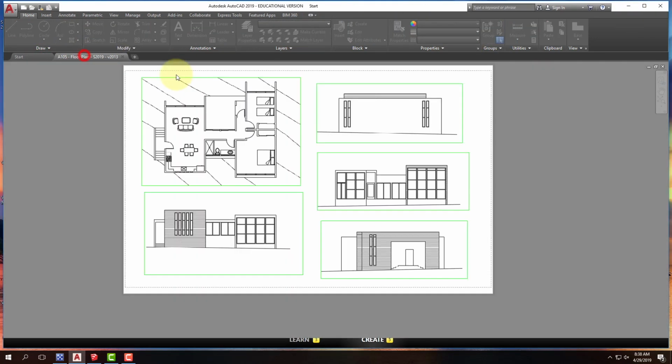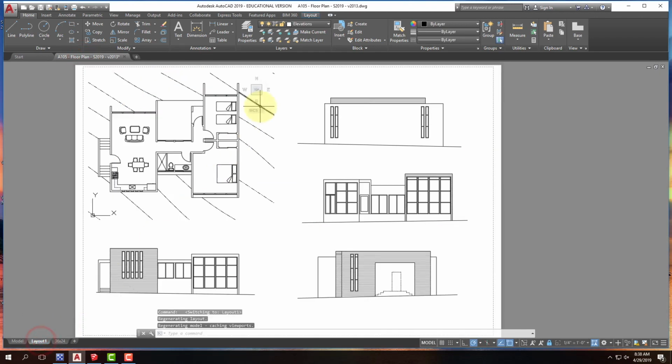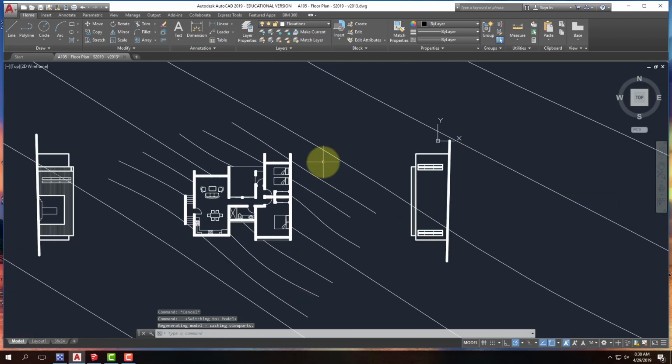When I'm working on this file, I could, in AutoCAD, go through and strip out all the pieces that I don't need. If I was in model space here, I could strip off the furniture and whatever, and I could delete it all. Or I can delete it in SketchUp. And it's a little bit easier in SketchUp, I think, because you can just delete layers as a group. If you've ever tried to delete a layer in AutoCAD, it's a little finicky, because if you have objects on the layer, then it doesn't want to do it. And so you end up with a command called QSelect, and you're selecting certain objects. And it's way more complicated. So we're just going to bring it straight in as it is into SketchUp, and then work with it from there.